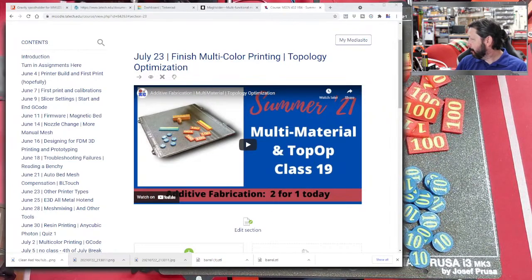I did get the Prusa MMU2S to work relatively reliably. I haven't printed any super long prints on it. Everything you print with MultiMaterial ends up being a longer print than it normally would, just because of the transition from one filament to the next and back and forth, and that might happen multiple times per layer even. I did load up a benchy, I think it was a 2-color benchy, and it was a 7-hour benchy, for instance. So I haven't printed any really long prints, but I have gotten several in a row with no intervention from me.